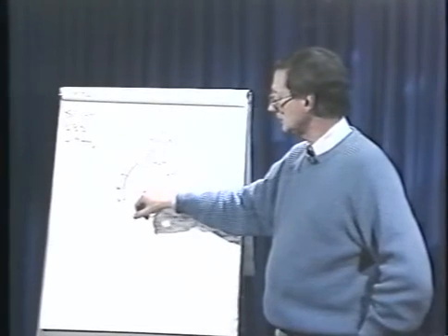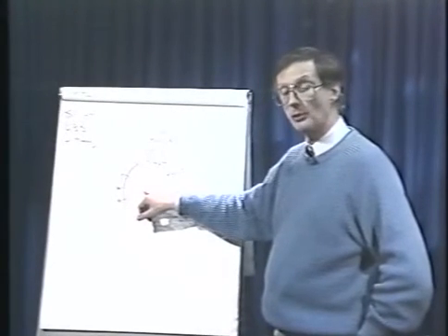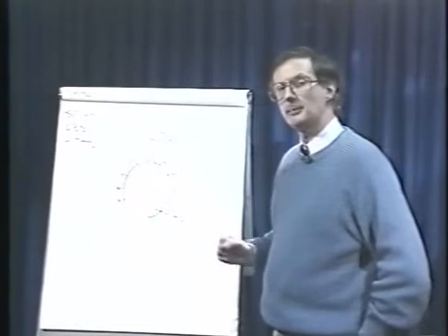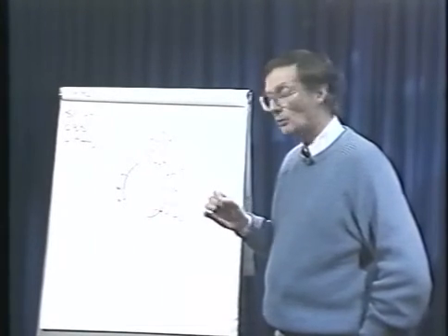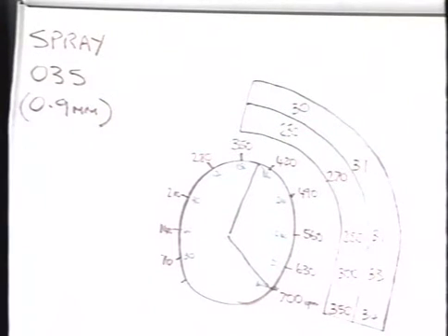An ideal starting point with an 035 wire on many applications, 1/8, 3/16, 1/4, would be to set the wire feed in the middle of its position, the 3 o'clock position, 560 to 600 IPM or 240 to 250 millimeters per second. You would have about 280 amps and 31 volts. That's an ideal simple starting setting.